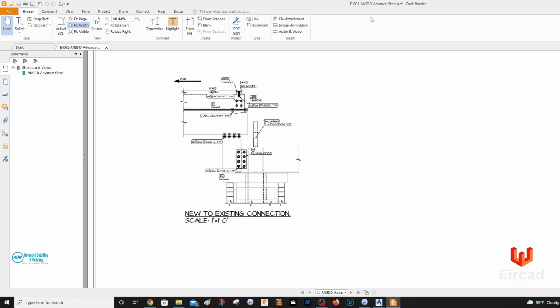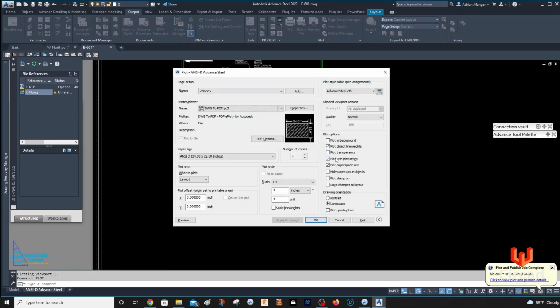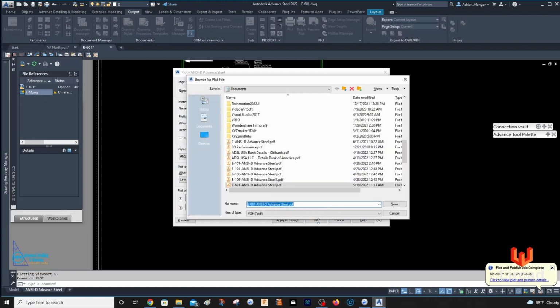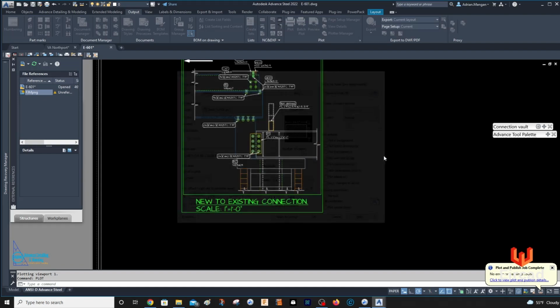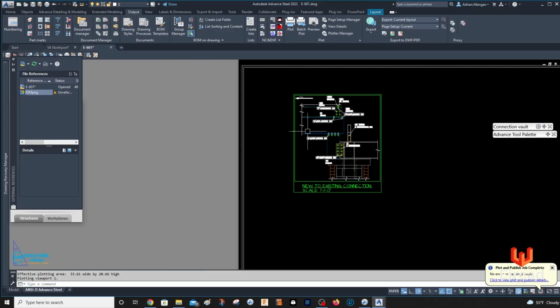Now sometimes you can, if you want, take off the object line weights. Sometimes it makes a difference, but mostly not for details. You can see how it looks a little better. It works good for plan views. If some of the lines are looking too thick, just get rid of the line weights altogether and it comes out pretty nice. So you can do that individually in drawings like that I just did there.